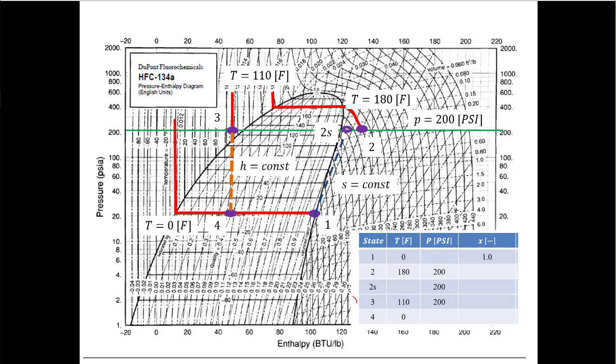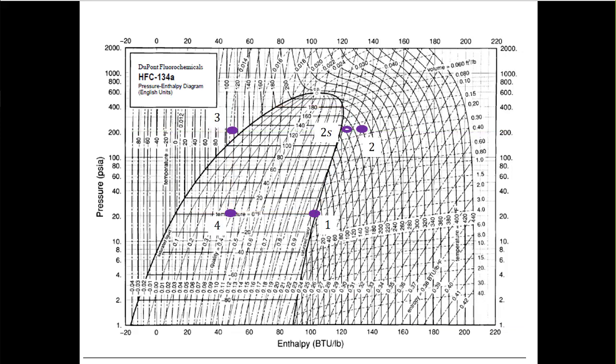So now I've located all my state points, which is cool because if I draw vertical lines down everywhere, I'll get values for all of the specific enthalpies. Now this next part you can't do if you're doing it yourself on an exam, but I can wipe everything away. This is another argument for having different colors, particularly when you're drawing the enthalpies. You can just draw vertical lines down.